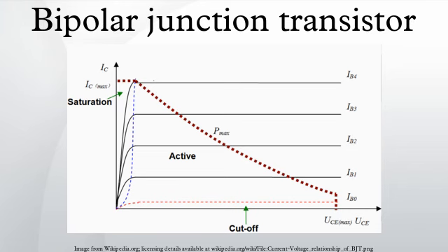If this is the case, the collector or emitter current is approximately proportional to the base current, but many times larger, for small base current variations. Reverse active: by reversing the biasing conditions of the forward active region, a bipolar transistor goes into reverse active mode. In this mode, the emitter and collector regions switch roles.